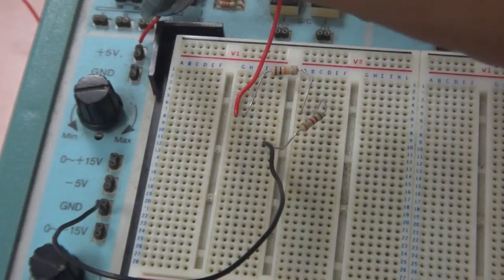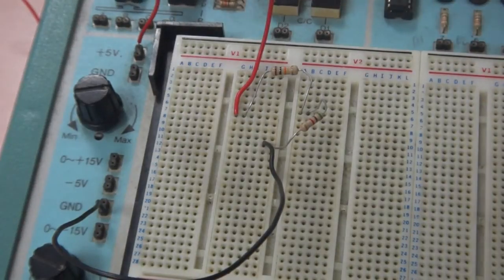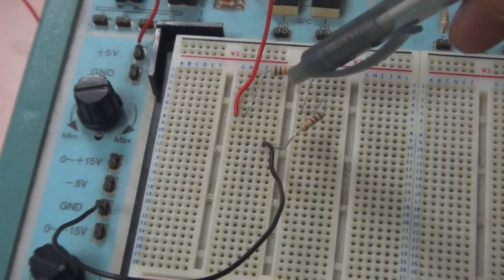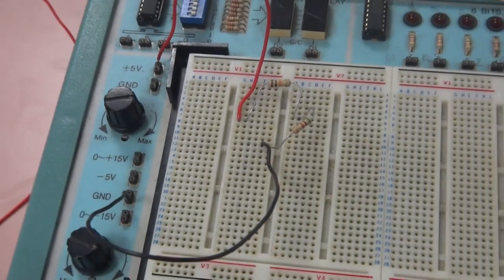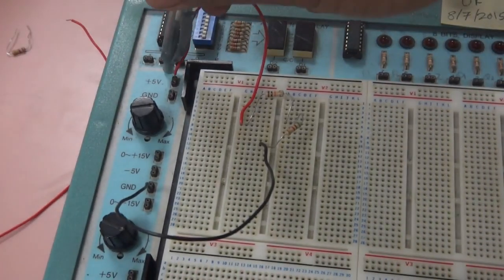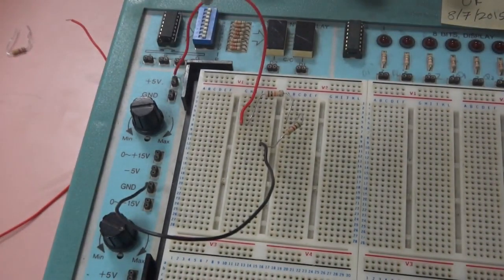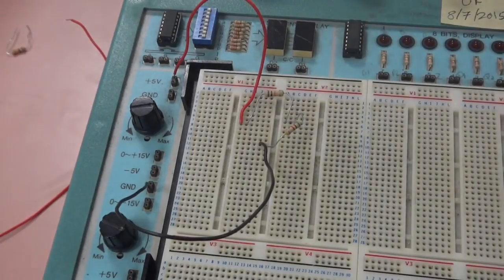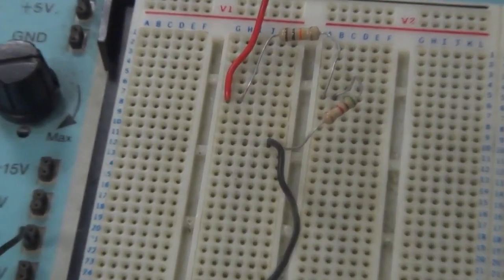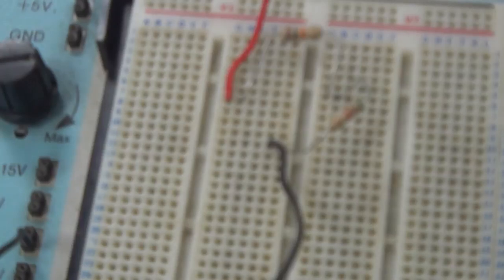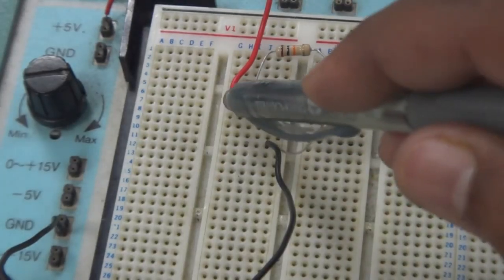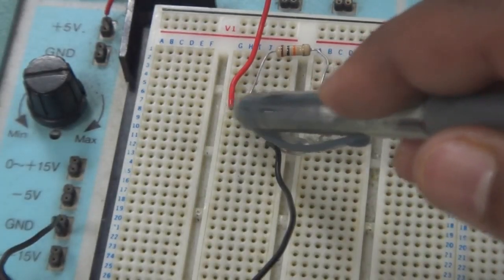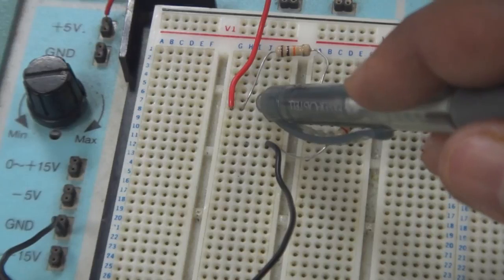And then from the source just now, the positive terminal is connected to your first resistor. So what we do is that we use a wire and connect from the 5 volt source to one leg of your resistor, and on the same row we place our resistor here, because we want to connect your source to your resistor.